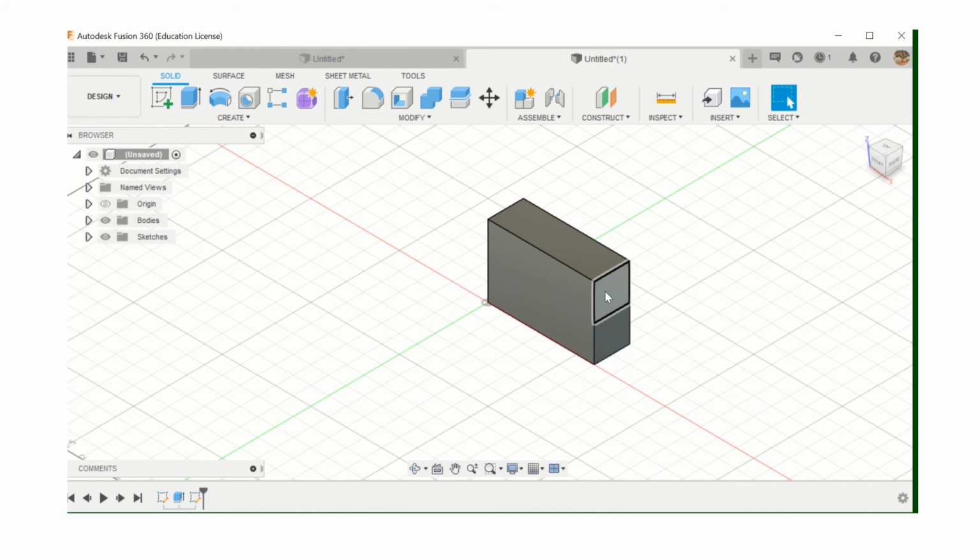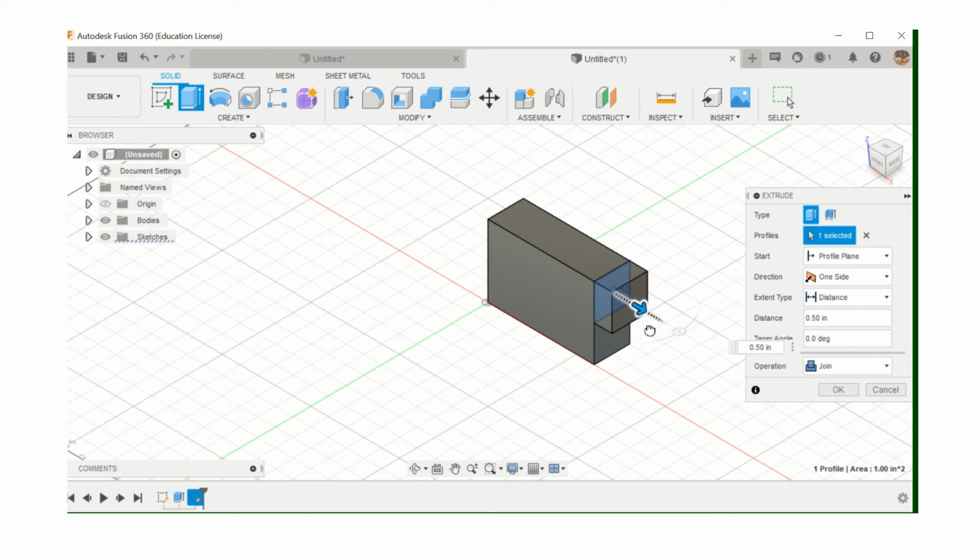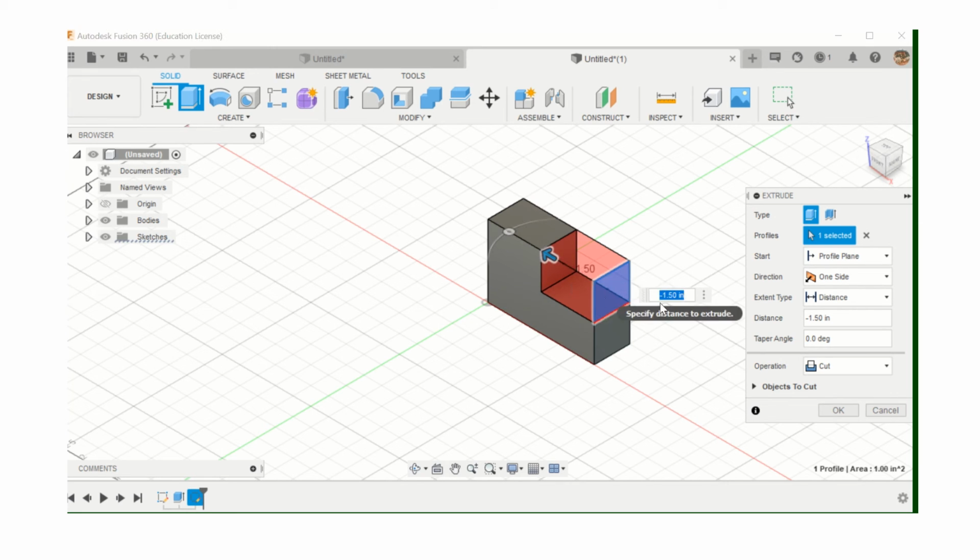And what we're going to do is, hovering over this surface, we're going to cut it in and do what's called a cut extrude. So I'm going to click extrude. Now notice that it's automatically pulling it out. You can also pull it in and it will cut. Okay, and notice how it's negative. For those of you that haven't ever studied vectors, that negative is getting into the idea of direction.